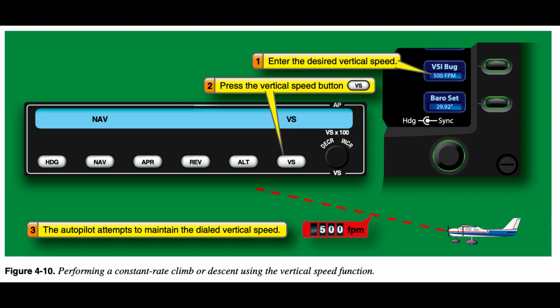You also need to monitor descent airspeeds diligently to ensure compliance with VNE/VMO and VA or turbulence penetration speeds if there is doubt about smooth air conditions. As discussed in the previous chapter, you should be cognizant of the power plant temperatures in reciprocating powered aircraft and bleed air requirements for turbine-powered aircraft.